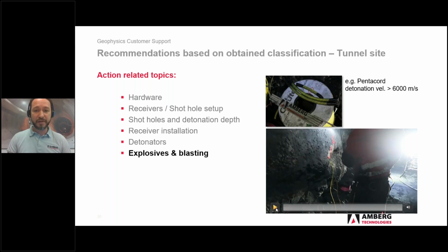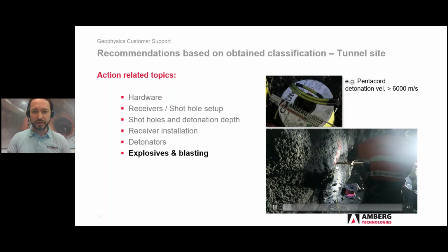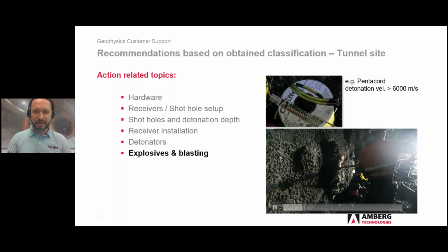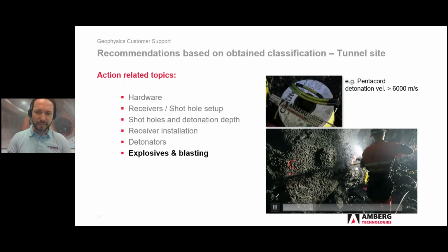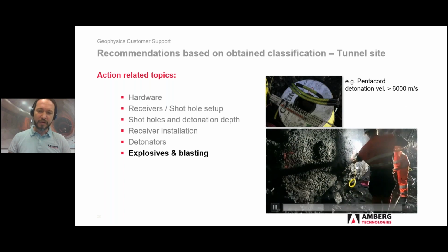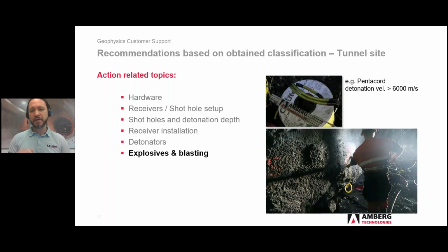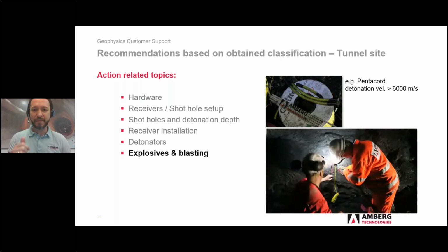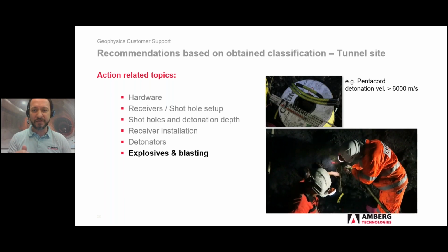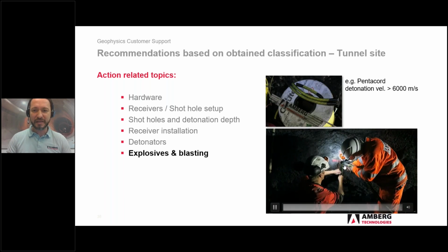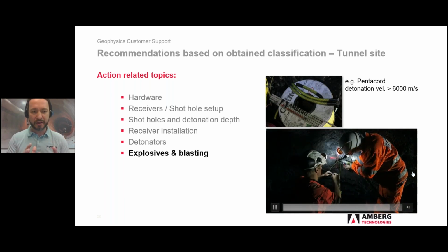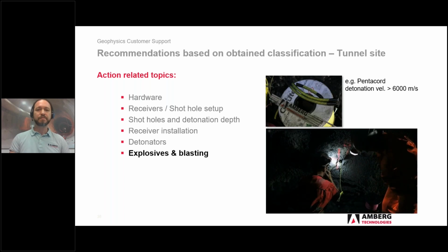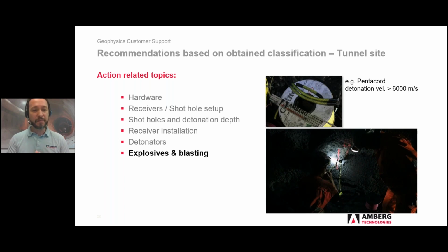The other important thing is to push the charge down the borehole. You see here, he is pushing it completely down. There is a mark at 1.5 meters on this rod, and he pushed it completely down. The most important thing here is to tamp very well, to do a good tamping of the charge. In this case, we're using water, and you need to saturate the shot holes with water. This is quite important because it minimizes the presence of the airborne wave I showed you in the previous example.